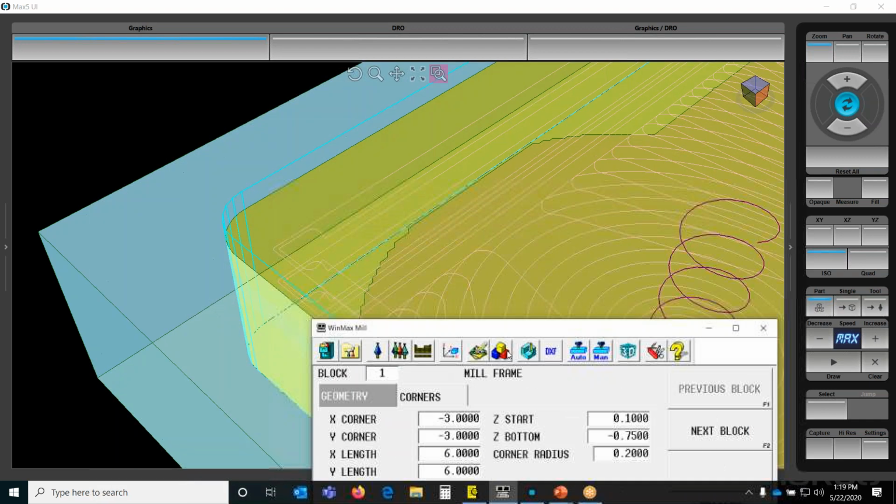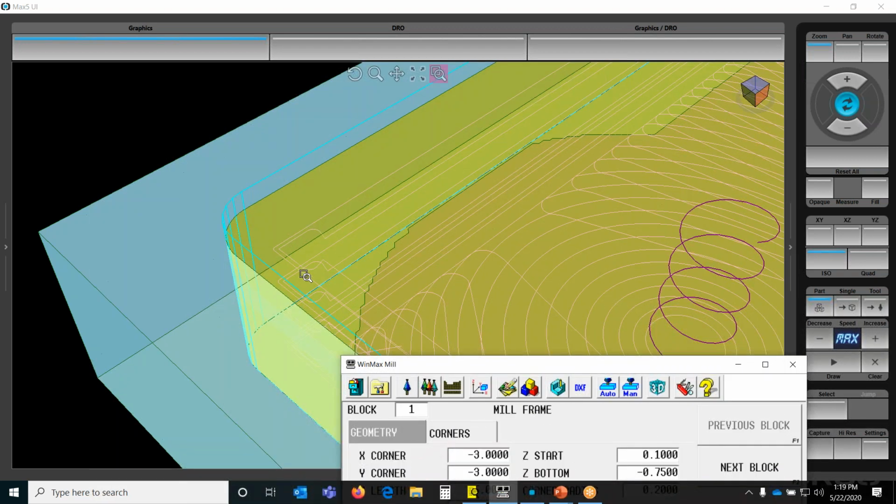So you can set this up as its own operation. This is a standard routine. This is like just programming a contour here. There's not going to be any of that constant engagement checks being done here. It's just going to take the tool that you gave it and go pick out those corners.